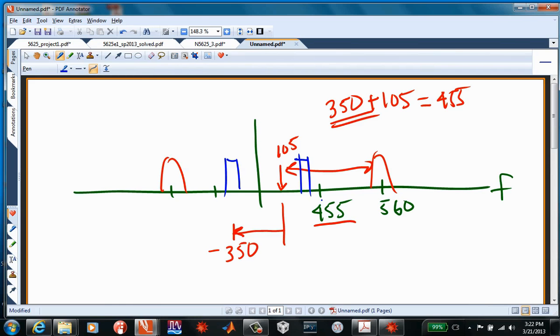When I say reality, I mean the fact that in analog signals, we have one line carrying our signal. If you had to have a complex signal, you'd have to have two physical wires to carry that complex signal. But in digital signal processing, not a problem. You just have to have a data structure that holds the real part and the imaginary part. And it's done all the time. And someday, I suppose that's the way we're going to have to teach it, because everything will be entirely in software or in the discrete time domain, and it only switches out to the real signal domain when it goes out the transmitter or right after it comes in through the receiver, the RF front end.